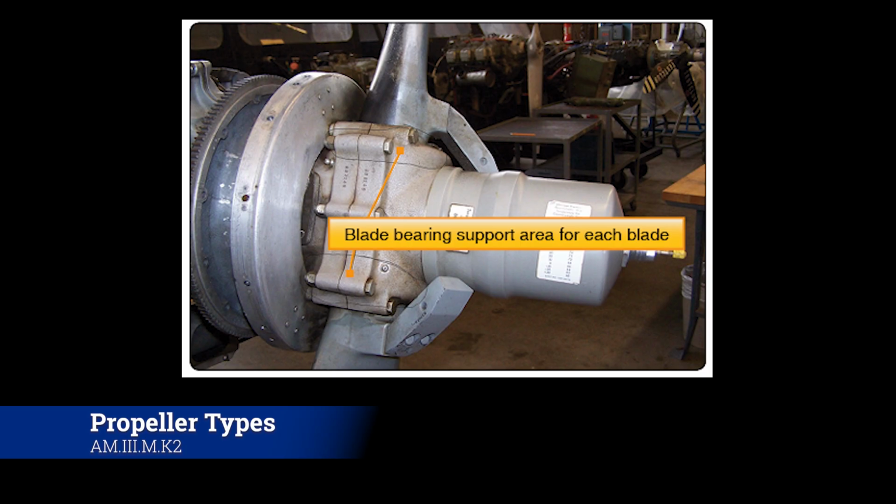By using propeller governors to increase or decrease propeller pitch, the engine speed is held constant, so the propeller doesn't overspeed the engine or drag it down. It's always right where you want it. That's why we measure it in manifold pressure. We set it to a certain manifold pressure, and that manifold pressure has to hold.